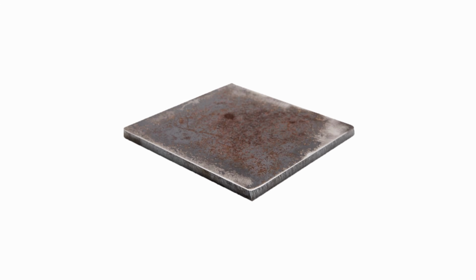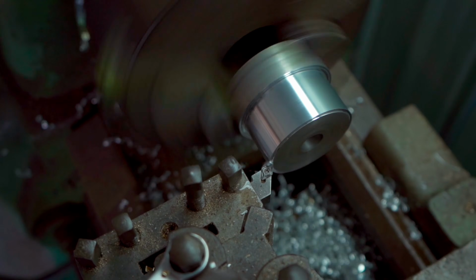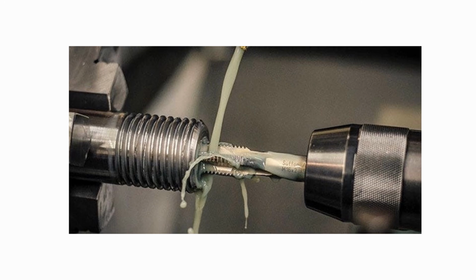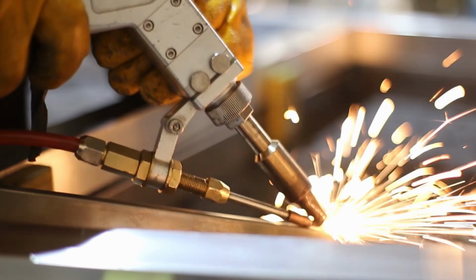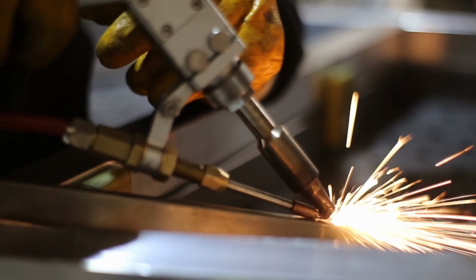But first of all, we should not harden the raw material of the steel. Because if we increase the hardness level of a raw material above roughly 40 HRC, machining operations such as milling and turning will become extremely difficult, or the tooling life will decrease rapidly. Also, operations like thread tapping will not be possible. The tapping tool could break inside the threaded hole. Additionally, welding will be challenging because hard material takes long to melt and fuse. So it is important to complete all the machining processes before the hardening process.